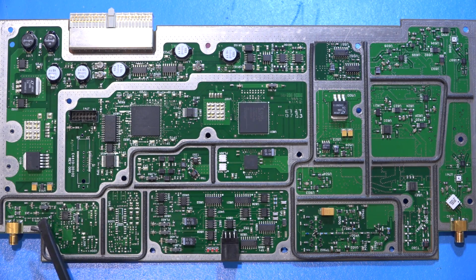So then from the other side we have the output, and you can see at the very end there is an amplifier block here. This is so that it can boost the output all the way up to about 14 dBm. So this is an Agilent branded part, probably not even silicon, maybe SiGe or GaAs, something that they've designed themselves. And here's another one over here. I believe that's another amplifier. So this is just an amplification stage.